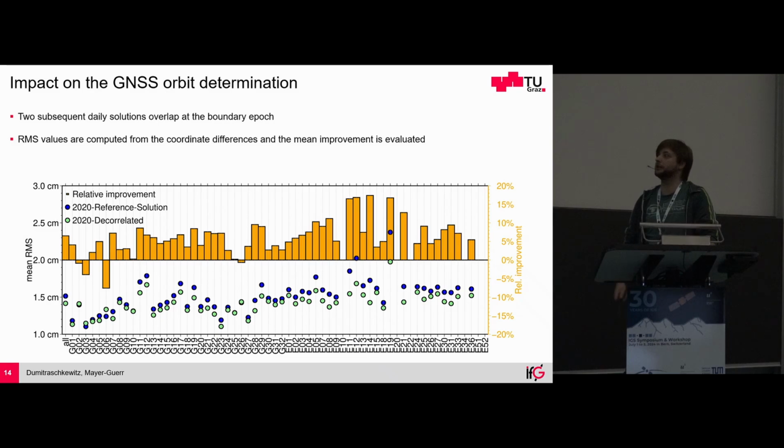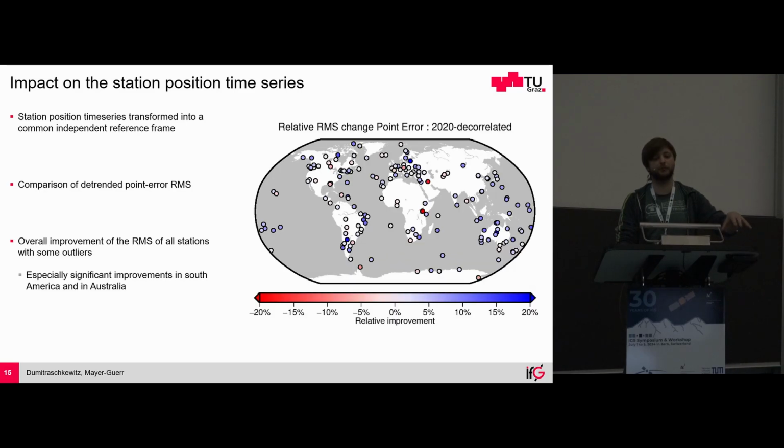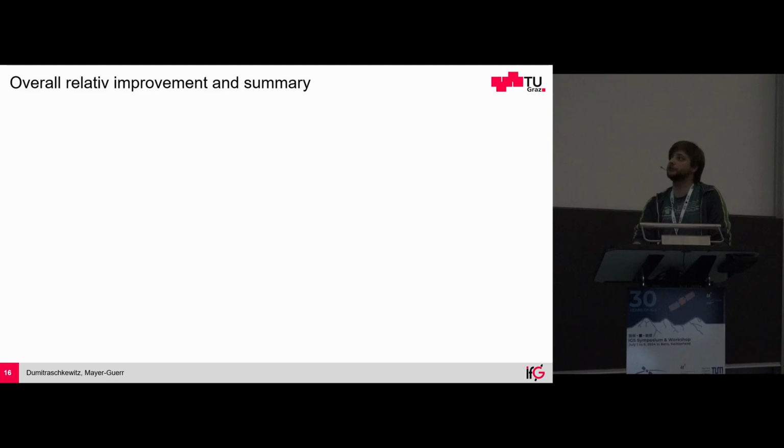Especially some Galileo satellites showed more improvements, but I would derive that due to the reason that in the selected stations, from the 200 stations, I think there were, if I remember correctly, a maximum of 70 stations that had Galileo, so I assume that stochastic modeling here would have a high impact on the less dense network of Galileos, especially when it also comes together with the X signals and so forth. So this showed that we have significant improvement in our orbit RMS, and for the stations we get similar improvements, which is very interesting.